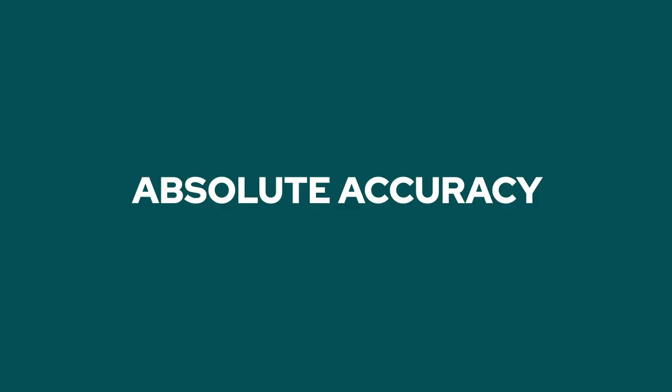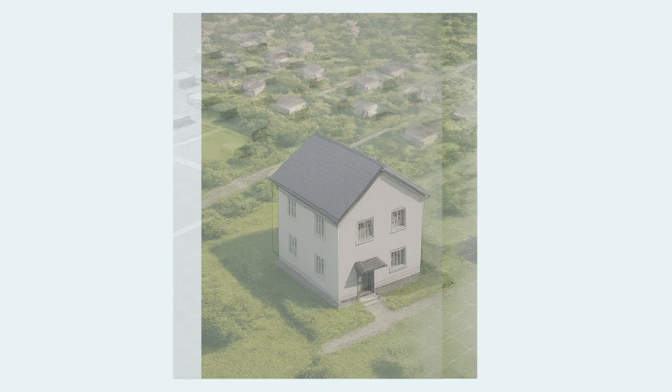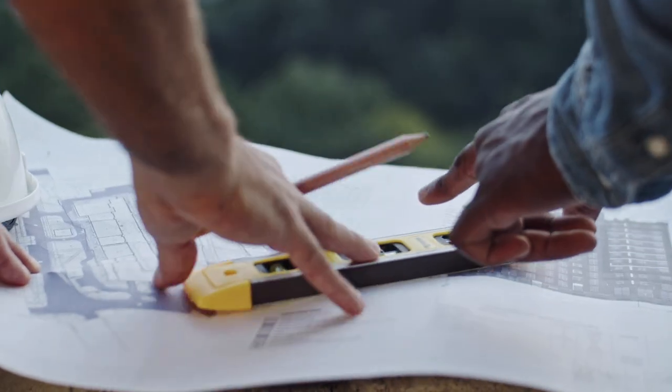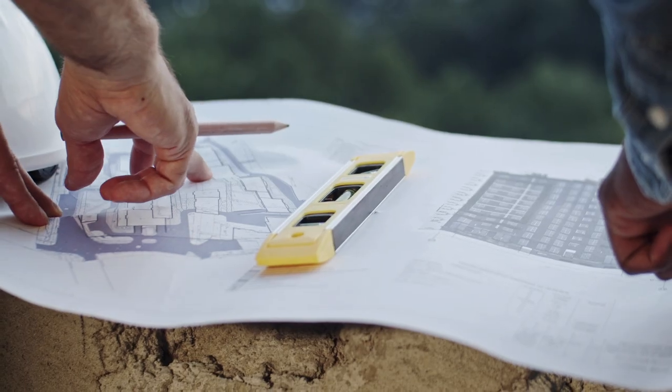Absolute accuracy is basically asking: you've captured this drone map and this drone 3D model, how accurate is it with respect to the real world? What I mean is, if you took this 2D map and 3D model created from drones and had to position it in the real world, is it in the correct place? If we sent surveyors out there to capture data with their own methods, like total stations and LiDAR, would they come up with the same 2D map and 3D model in terms of positioning? And can we assume a certain tolerance, a certain error rate, with respect to how close or far that 2D map or 3D model is?